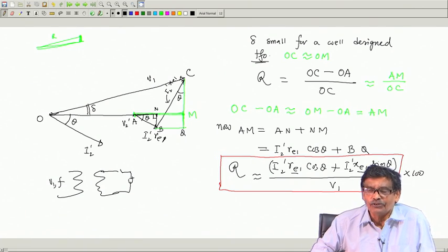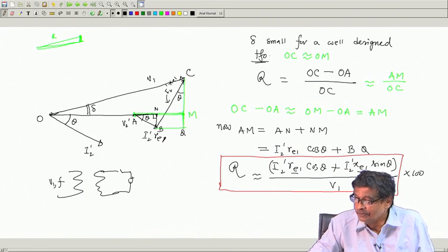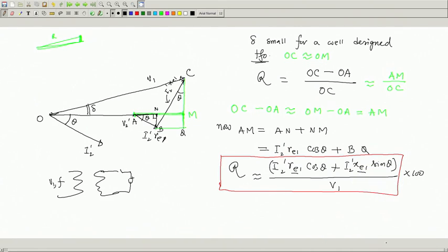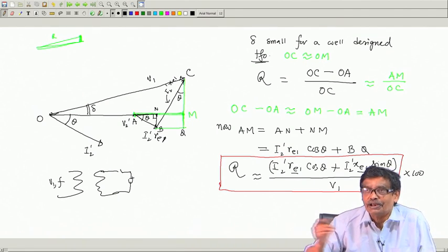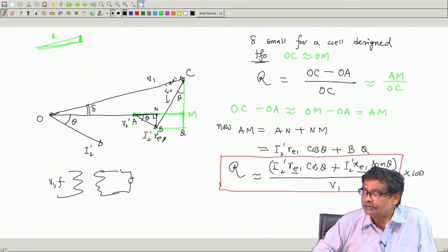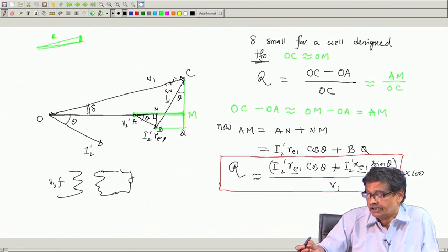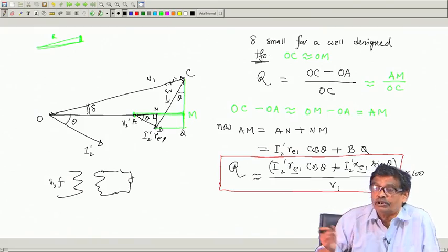Okay? Because open circuit, short circuit test are very simple tests. I will carry them out, find out these values, then tell me any load current the transformer is delivering, of course, up to rated current, and at what power factor. You give me these two pieces of information, and I will be able to give you the value of regulation, how much voltage will drop.